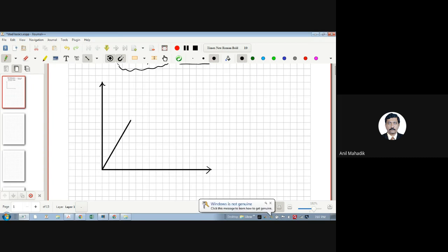Generally, this is the stress strain graph of mild steel, where we get an exact yield point here, and the stress corresponding to the yield point is 250. This is your graph, sigma, that is stress, and this is your Fy at this point, the yield point.